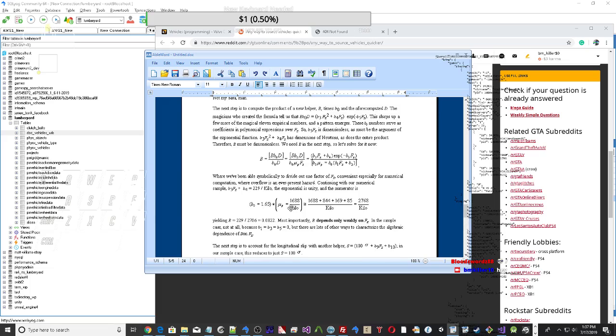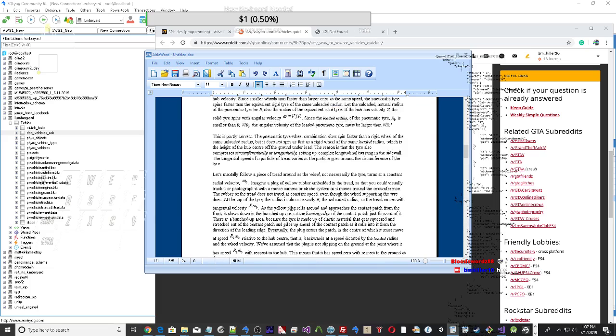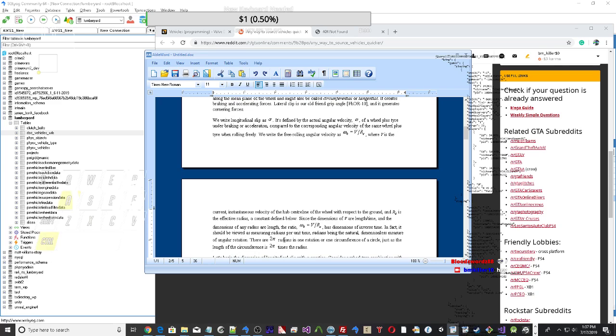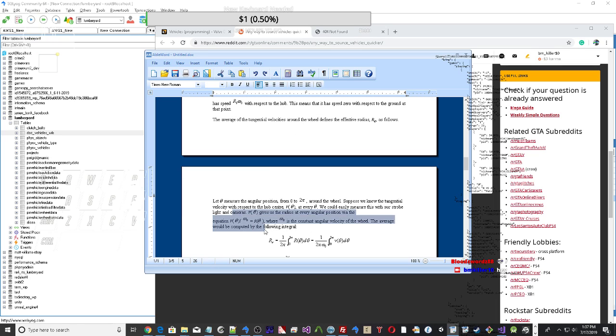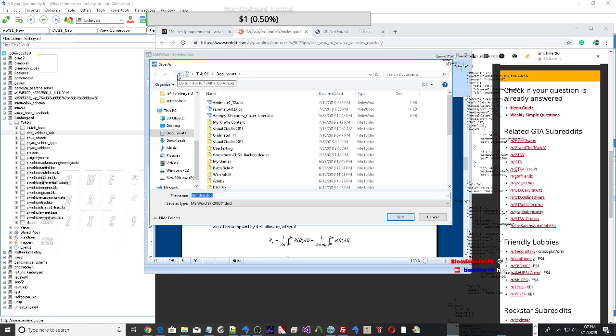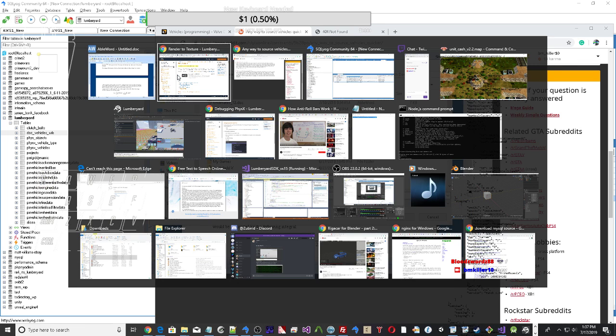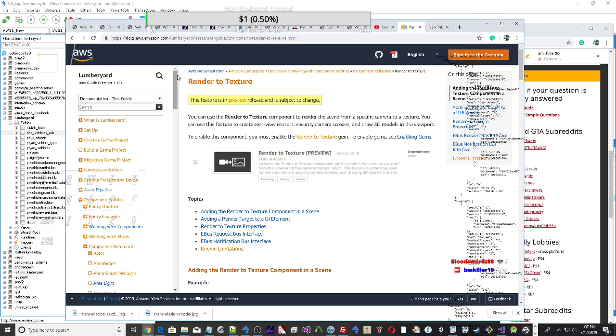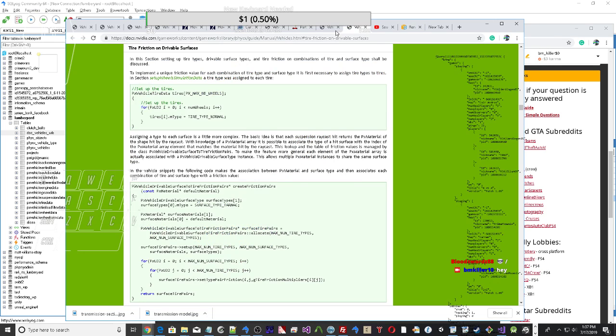Tire force application point 0.3 meters below rigid body center of mass. tireForceAppCMOffsets[i] = PxVec3(wheelCentreCMOffsets[i].x, -0.3f, wheelCentreCMOffsets[i].z). } Set up the filter data of the raycast that will be issued by each suspension.